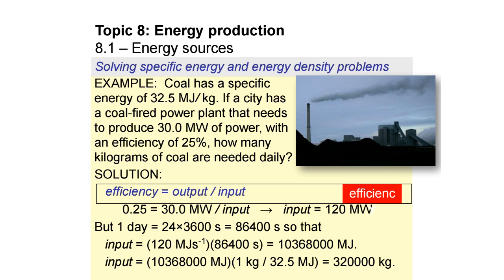And here we go. You've got your value, 120 megawatts, which is ridiculous. 120 megawatts, that's how much energy you need per second. All right. You multiply it by 24 times 60 times 60 to give you how much you need in a day, right? And then you just need your fuel, megajoules per kilogram, to work out the amount of mass you need.